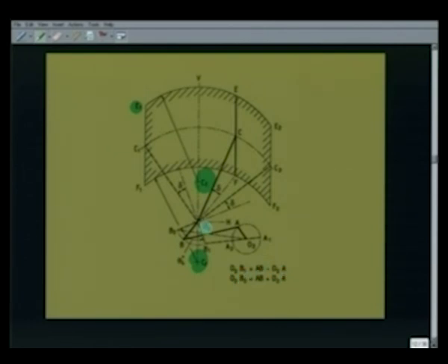Once I have got the extreme positions of link 4, I draw O4C2 and O4C1 corresponding to O4B2 and O4B1. Because link 4 is a rigid link, the same angle delta is maintained between the line O4B and O4C. Once we get the extreme positions of the point C, I draw the wiper blades, which always remain vertical because of the parallelogram linkage, as E2F2 and E1F1.